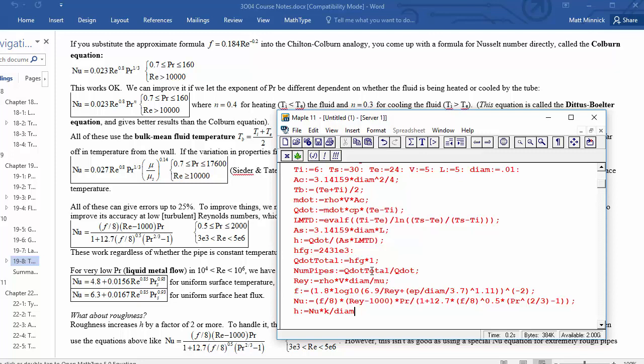So then in solving that for h, we'd figure out our new formula for the convection coefficient, if we were to use the fluid properties to figure out the Reynolds number, and then use that to figure out the friction factor, and then use that to figure out what the Nusselt number should be, and then use that to figure out what the convection coefficient should be. But a lot of this is based on experimental fits and things that we didn't really know and had to look up and guess, like the roughness.